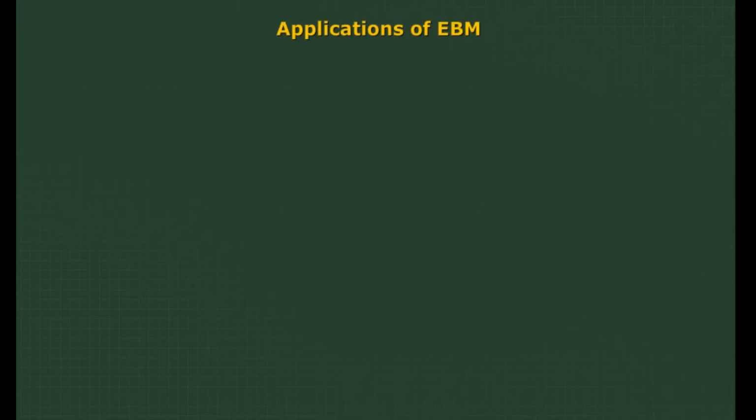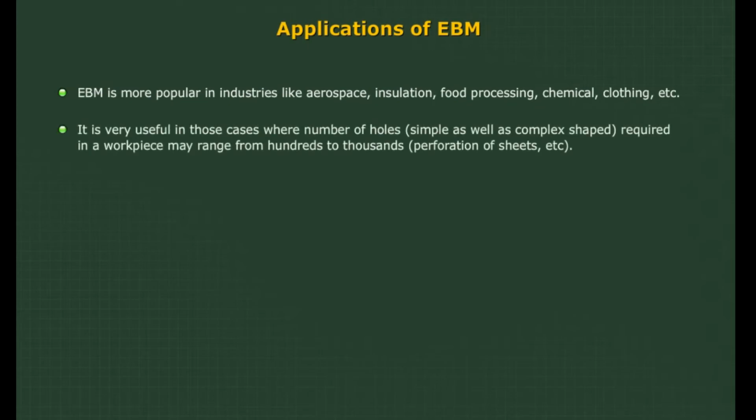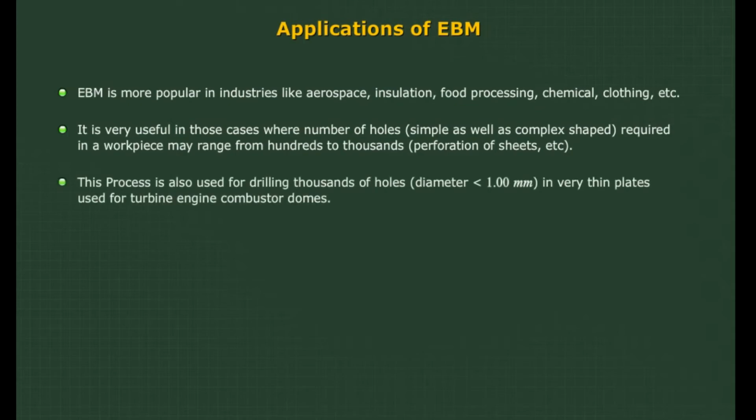Applications of EBM. EBM is more popular in industries like aerospace, insulation, food processing, chemical, clothing, etc. It is very useful in those cases when the number of holes, simple as well as complex shaped, required in a workpiece may range from hundreds to thousands, perforations of sheets, etc. This process is also used for drilling thousands of holes, diameter less than 1.00 mm, in very thin plates used for turbine engine combustor domes.